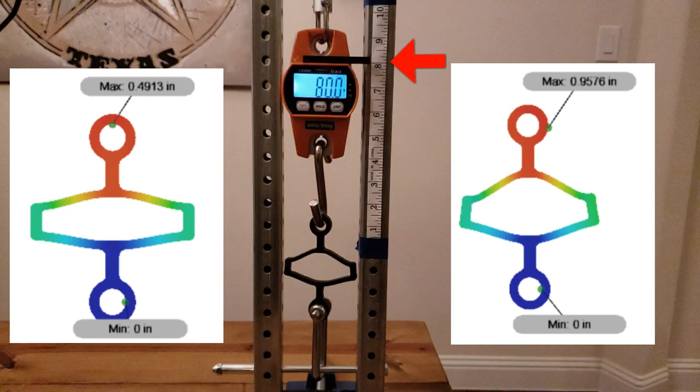So we're just above 8 inches on the flag, so maybe we had an actual displacement closer to 1.1 inches, but I'd say we are exceptionally close, probably within 10 to 15% of our estimated value. And obviously our linear simulation on the left was just catastrophically wrong. We would never believe the result of a linear simulation with this much displacement.